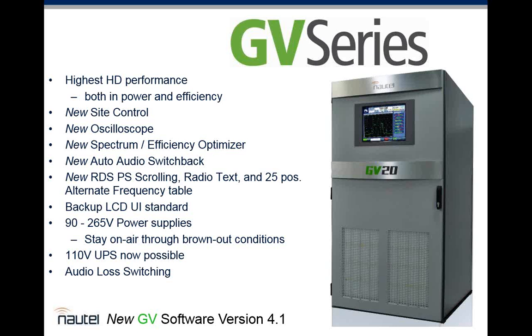So, tying up a few loose ends on the GB series, what we've been talking about today is the highest HD performance in both power and efficiency. It has a new site control, new oscilloscope, new spectrum efficiency optimizer, new audio switchback, RDS PS scrolling radio text, 25 position alternate frequency table, and a backup LCD user interface internal, just in case the screen in the front panel stops working. Power supplies will work down to 90 volts. You can stay on the air through brownout conditions at reduced power, and that means a 110 volt UPS is now possible. And there's audio loss switching built into the transmitter.